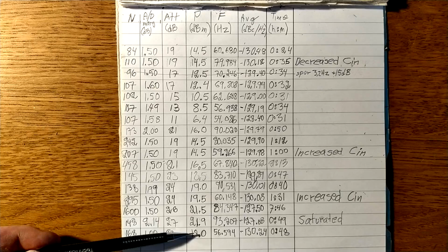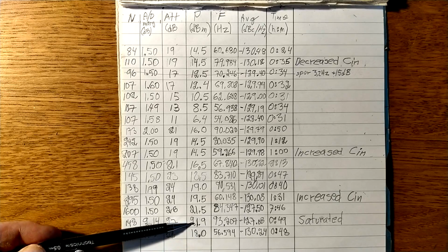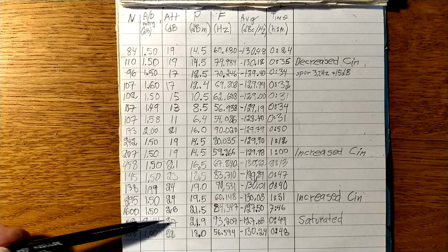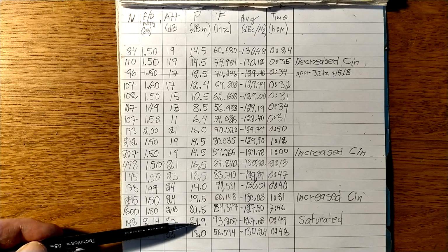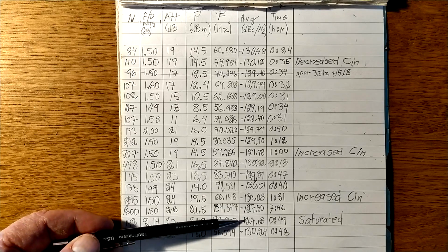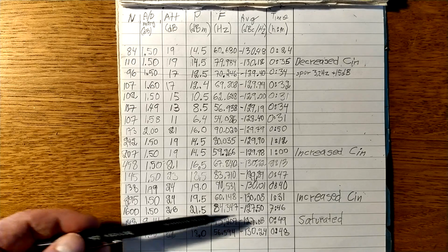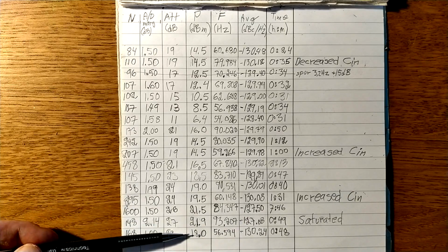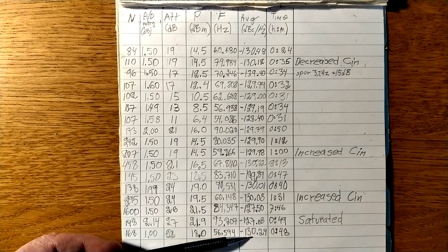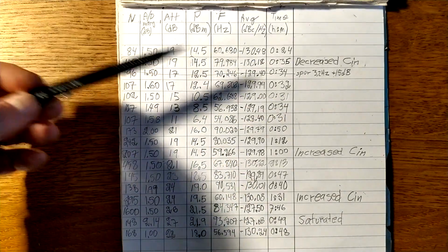Anyway, the last data point here is a point where the unit is saturated. So reducing the tuning capacitor did not increase the power. This is a measurement very close to the saturation point, and performance has degraded significantly. And here 18 dBm seems to be a reasonable level where to run the oscillator. So I went to it and found 130.2. That is close to the best values I have seen.